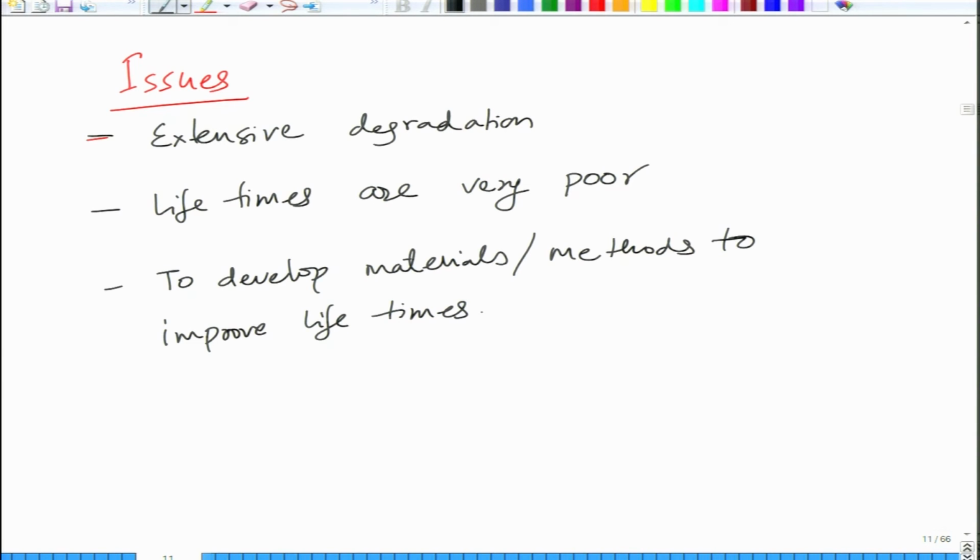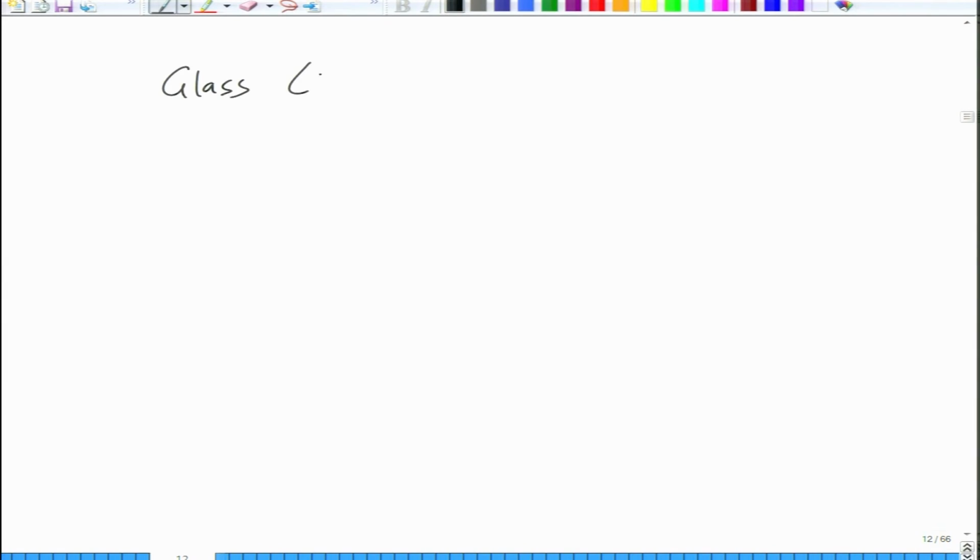These materials have shown efficiencies of the order of about 23% as of now. They have certain very good qualities, they have very good light absorption, they are easy to make, they are solid. So, basically this device is solution processable, most of it. Just like organic solar cells, when you make this device, so manufacturing, you start from glass substrate, FTO coated glass which is bought from the market, you pattern it, after patterning you deposit TiO2.